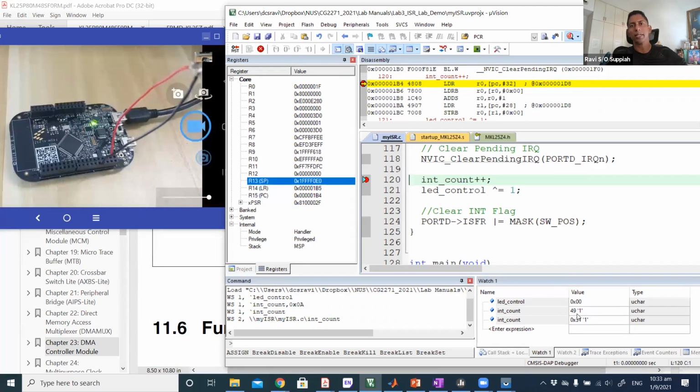It will help you a lot to check whether everything is correct. Because if you do this and it's not working, it could be the switch is faulty, the LED is faulty, or there is an issue with the code. So this helps you narrow down that the interrupt is correct, the switch is correct, and then you can look at other things that could be an issue. All right, so that is basically what you need to do.